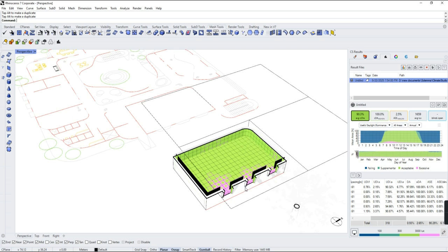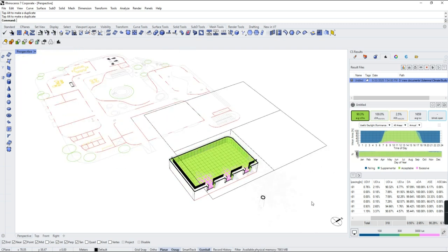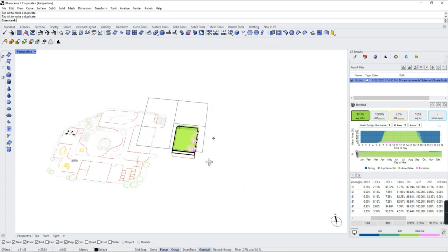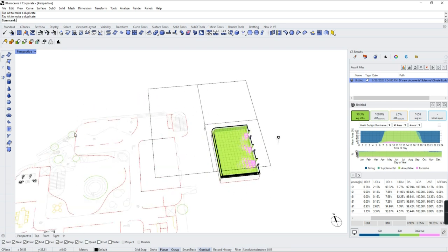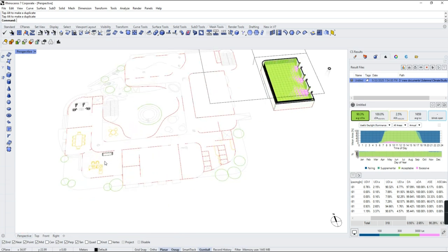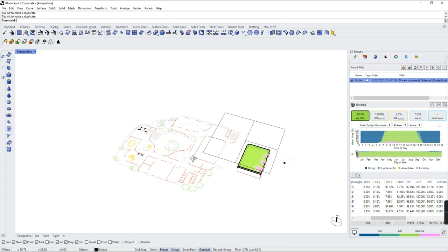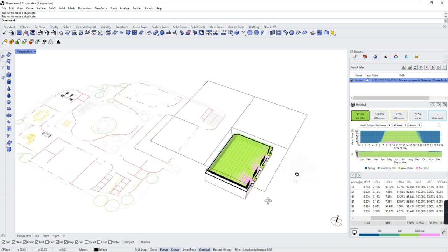So yeah, I think that should cover it, and you should do it for important areas. For example, this one was lying towards the east. If you look at this space, it is lying towards the north, so you might want to have a large window. Figure out what works for which direction. This particular one might require something else because it doesn't have any window. So look at least 3 spaces, and for every space try working out 2 to 3 window iterations.